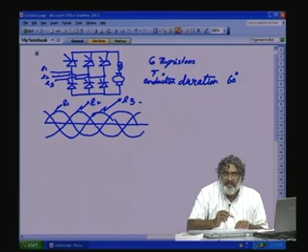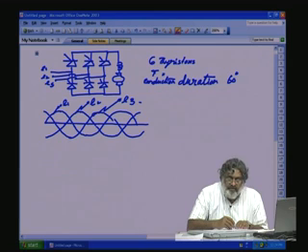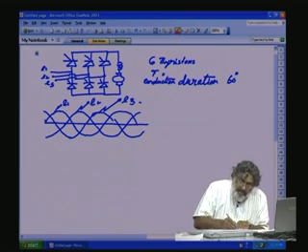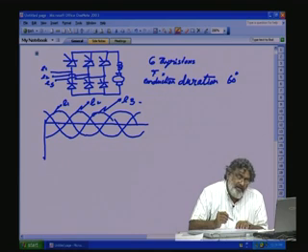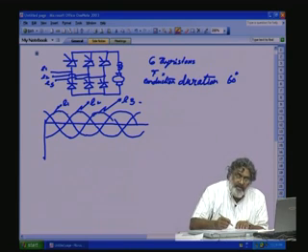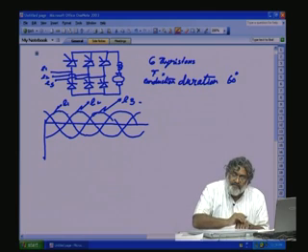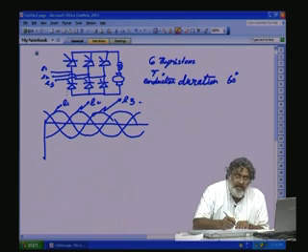When the E1 phase is at this instant, if you take omega t equal to 0 here, sin omega t, you are starting from here. Let us take E1 to turn on, E1 is positive here. So, from this point to this point, for the positive side, E1 is positive and T1 will be conducting.